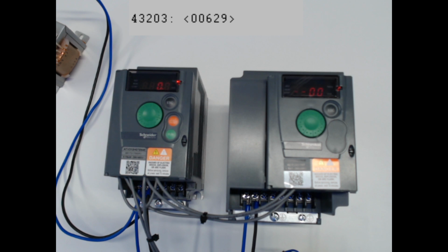Okay, so you observe that now I'm going to try to reduce my sensor value. If I reduce it to below 50, I expect the drive will pick up. So now we pretend that everyone is turning on their taps and the pressure in the manifold drops.